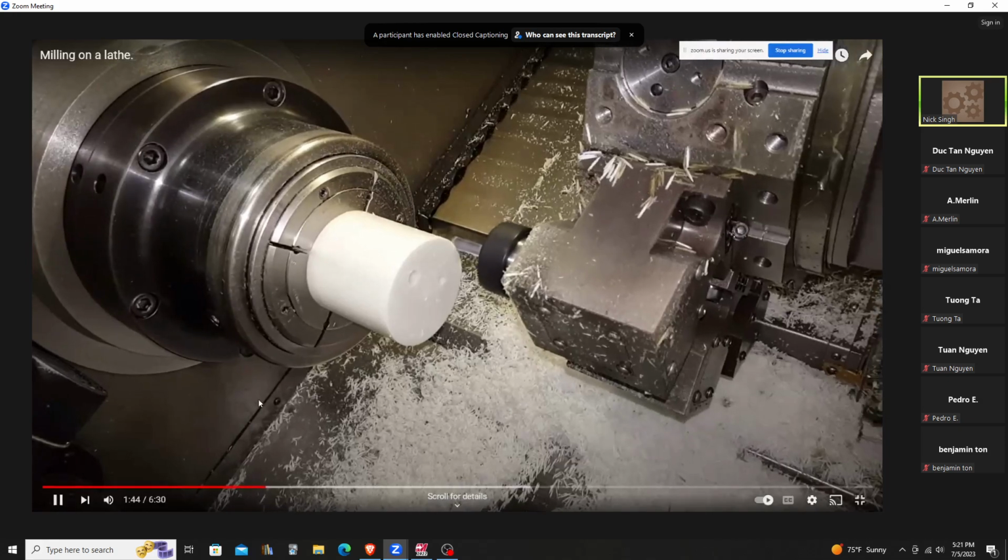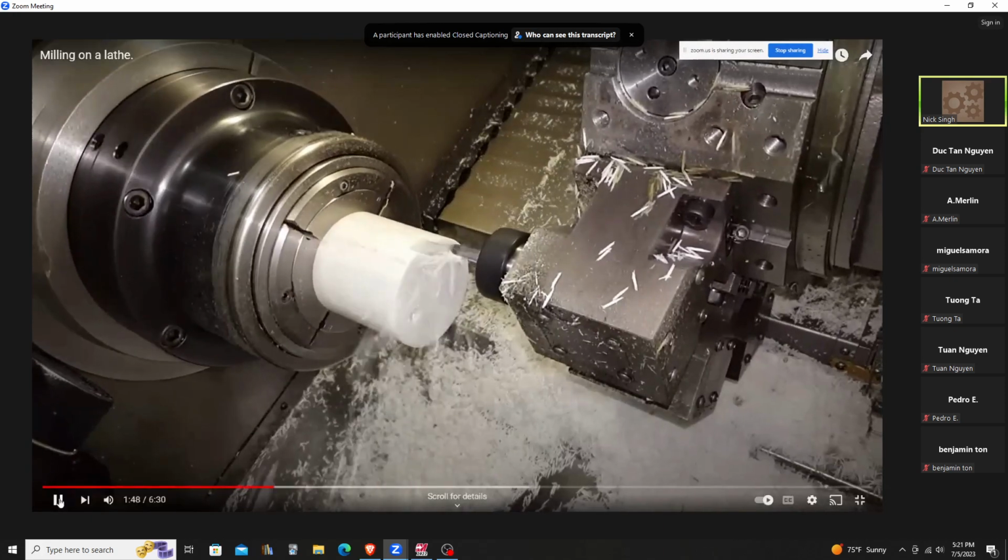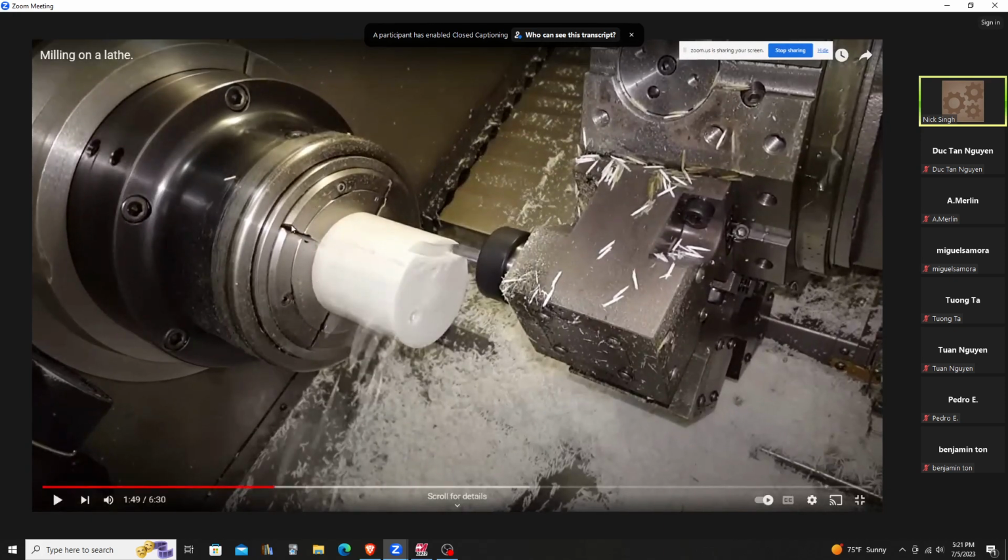And see that now? If you look at how slowly the spindle is moving, that spindle becomes the C-axis now. It rotates in degrees, anywhere from 1, 2.1 to 2, 3 degrees up to 360 degrees. That C-axis syncs with your X-axis, and it can create any type of shape. It's working just like your mill machine, guys.